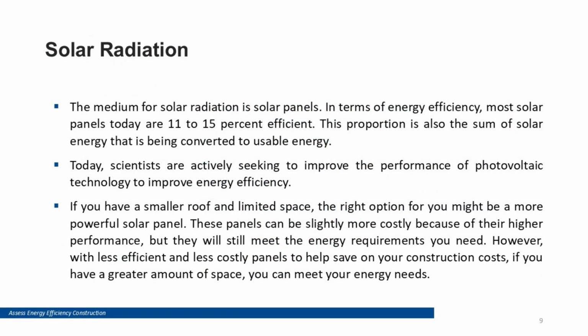Solar radiation. Solar gain can reduce heating demand in winter but cause overheating in summer. Passive control uses orientation, shading, glazing selection, and thermal mass to manage this balance. Solar PV and solar hot water can further reduce operational energy, but demand reduction usually comes first.